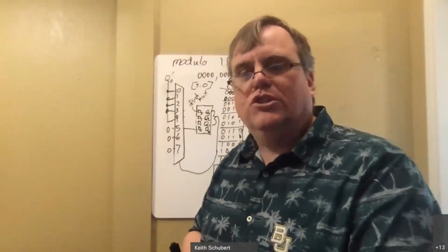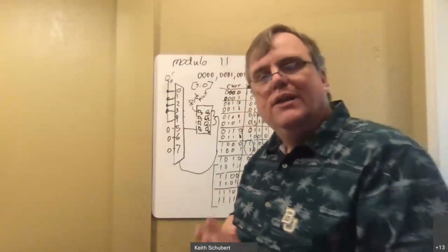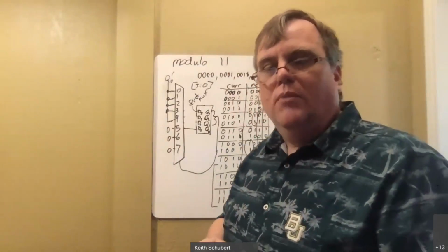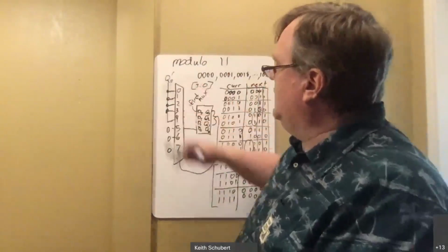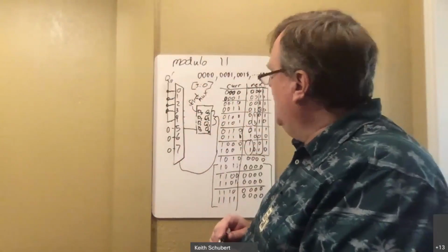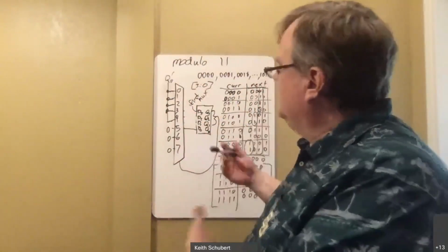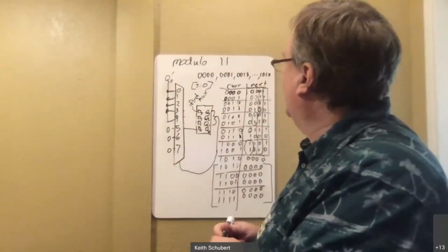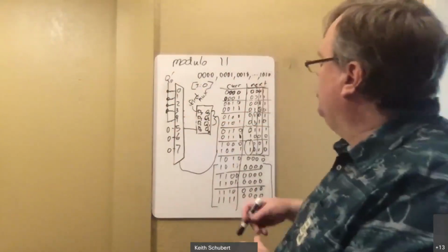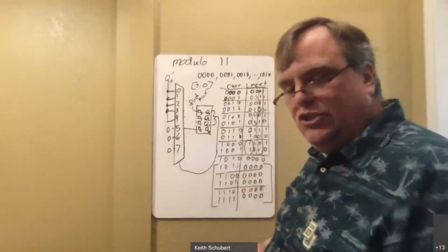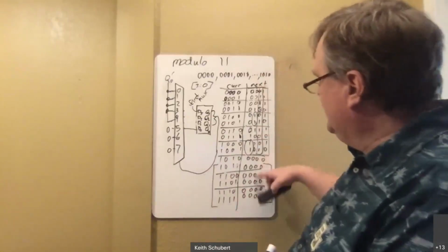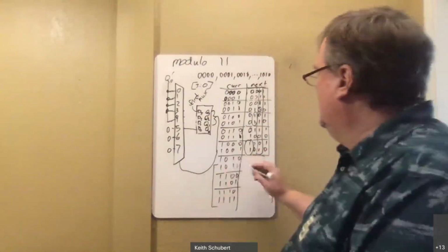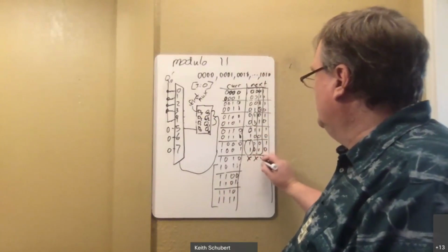Let me give you a hint towards the challenge problem. If you notice, it's smaller. I halved these. So since it's halved, you have to have more options inside these. So you have to be able to rearrange them. And the trick towards this problem is these ones that are all 0 down here, make them X's. So they become don't cares.